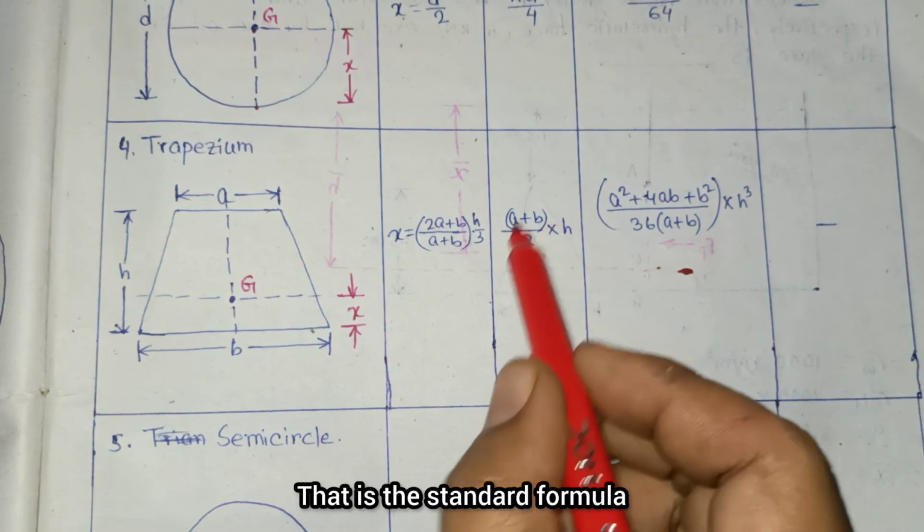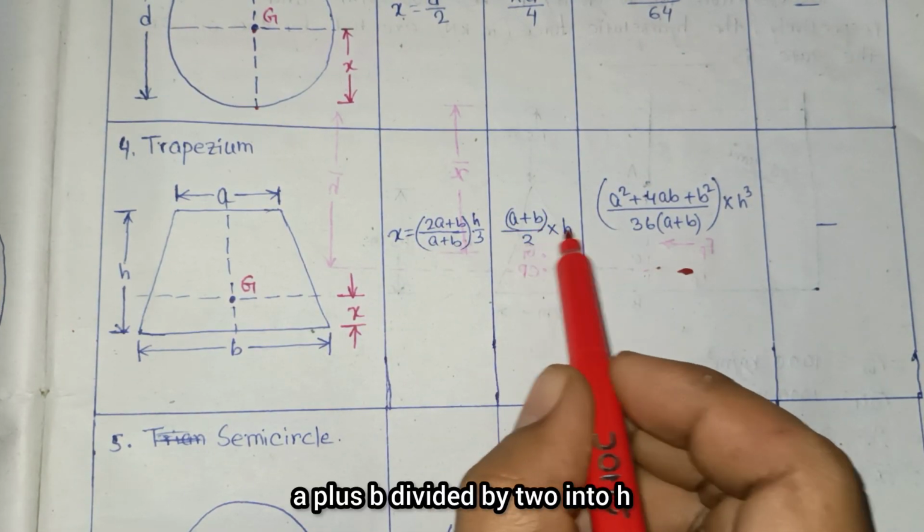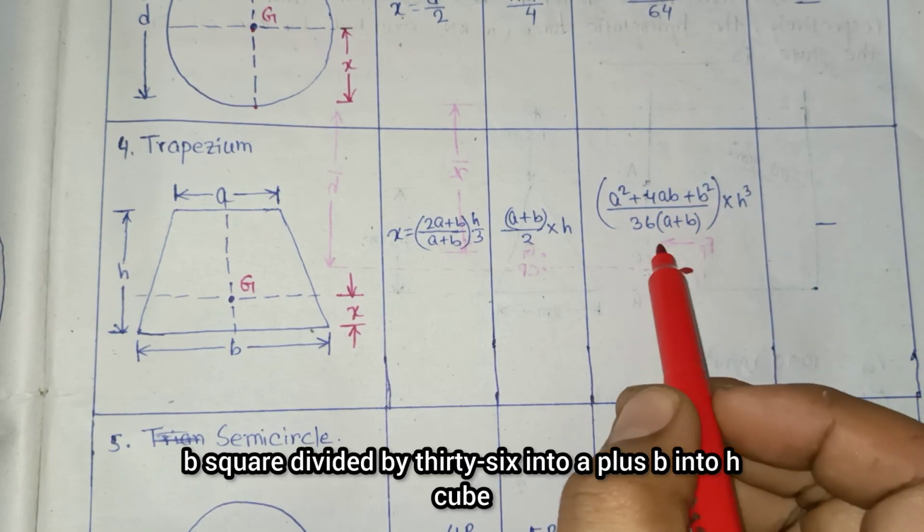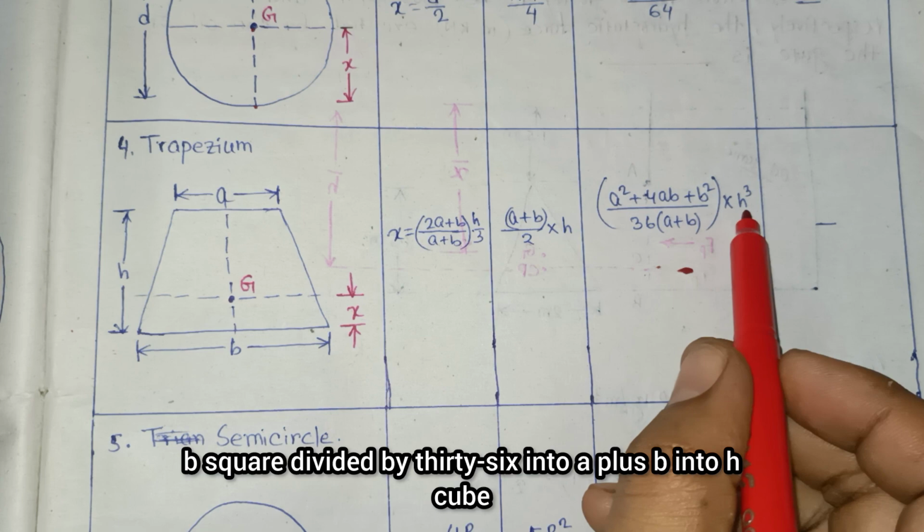And what is the area? That is the standard formula, (A plus B) divided by 2 into H. Okay, and what is the value of Igg? That is (A square plus 4AB plus B square) divided by 36 into (A plus B) into H cube.